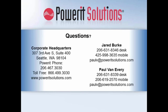And then as you came to the end of your billing cycle, you would go back in and lower that set point down to 2,000. Because the utilities are going to charge you that peak demand charge based upon the highest occurrence during your billing demand cycle for that month.